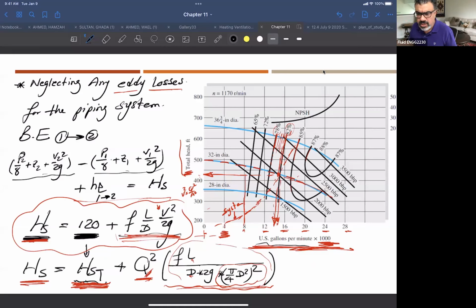Versus another application where there is already a difference in energy in the direction of the flow, but this energy difference is not pushing that much fluid inside the system. So we put the pump there in order to boost the flow, to increase the flow rate in the system. So in all cases, we are designing this system by looking at the diameter of the piping, and what components will be added: valves, elbows, and all this, right?